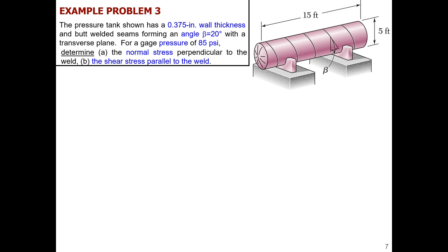Okay, so our simplification here again is like this. We still have our cylindrical system, so we have sigma 1 and sigma 2. Right, principal stresses: hoop stress sigma 1 and longitudinal stress sigma 2, which we can calculate based on the applied pressure P, which is given. But then we will need to do something with that because we need to calculate it in a certain direction. Probably we will need to use what we learned from the Mohr circle, right? So that's to see how that stress will change at a certain angle. But let's start from calculating sigma 1 and sigma 2 for now.